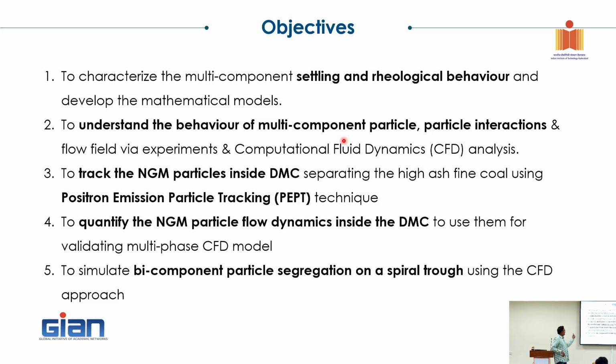So this is where I'll take you through certain fundamental aspects which are very important when you go and understand the mechanism, especially for finer particles, like in the case of hydrocyclones, or even to the extent of treating very fine particles. The particles' settling velocities and rheological behavior are important, which we always see in a disconnected way. But otherwise, in real separation, your particles are not single particles; they are multiple particles. And when the particles consist of a very fine fraction, your rheology also gets significantly affected.